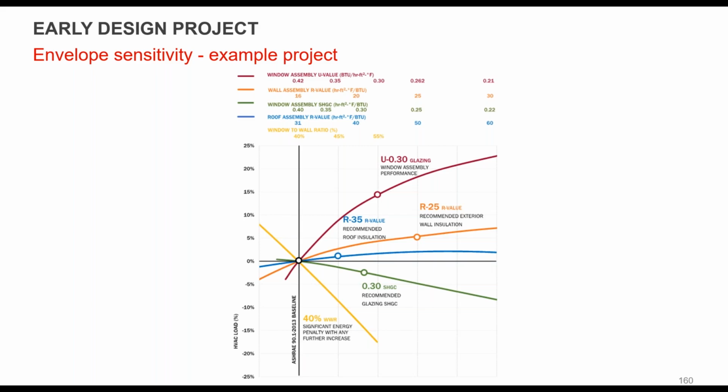So that's a direct relationship, almost 1-to-1. SHGC is a little bit lower, but not quite the impact. Insulation levels for the roof and the walls, and you see recommended levels there, and overall U value, you can see how that affects that as well. So having a look at what it's sensitive to is very important as well.